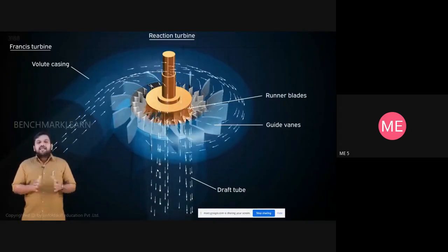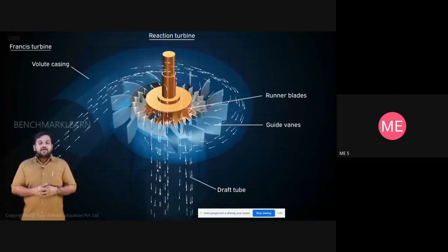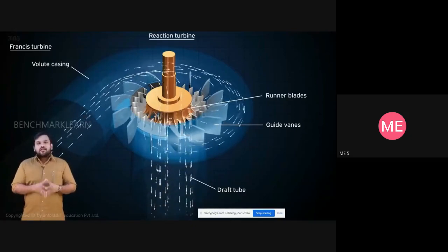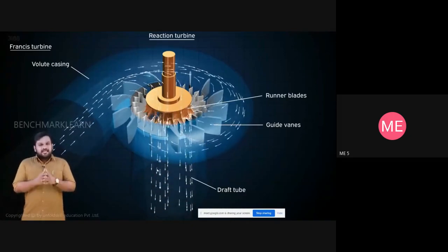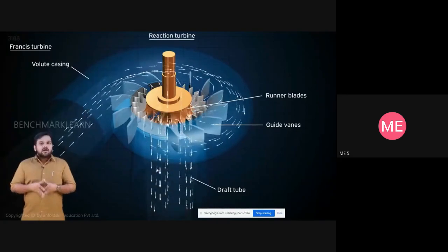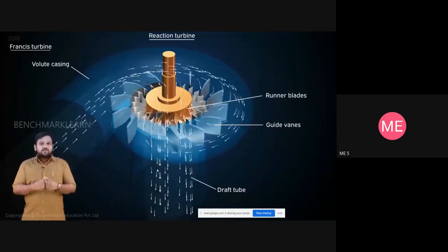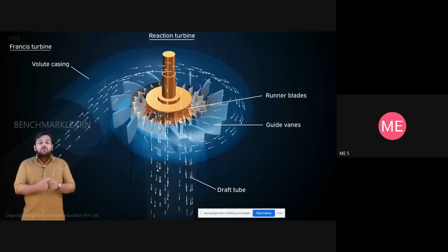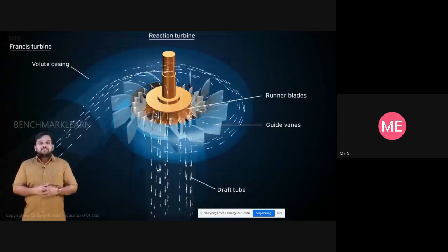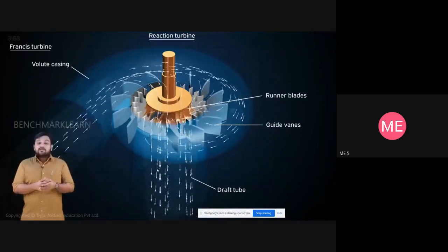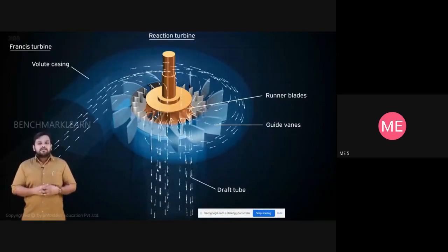During the process, the pressure energy of water is converted into kinetic energy. So, the water, after passing over the runner, possesses low pressure. The kinetic energy is also converted by the reduction in velocity when it flows over the blade. It is the net pressure difference from the inlet to the outlet which determines the energy from the turbine. To achieve a maximum difference, the outlet pressure is kept very low, sometimes less than atmospheric. This will prevent the natural flow of water from the outlet.